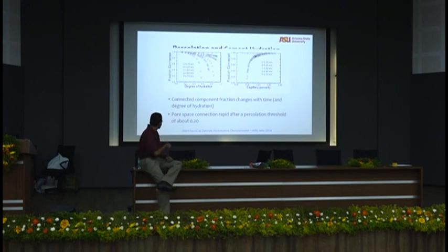You see here, you need 85% degree of hydration of cement to close off all the channels that are available for something else to go in. And it's highly unlikely that you will get 85% of the cement to be hydrated. Whereas if you have a water cement ratio of 0.35 or 0.4, you need only lower amounts of degree of hydration.